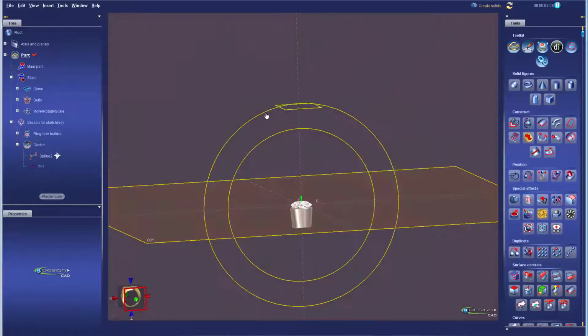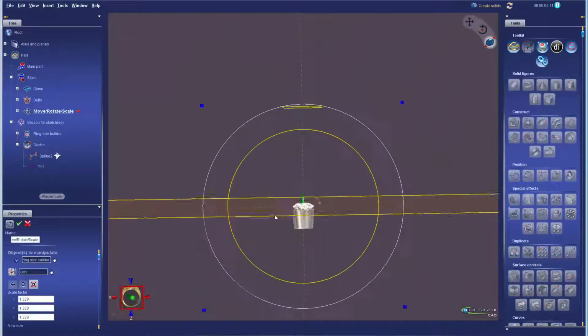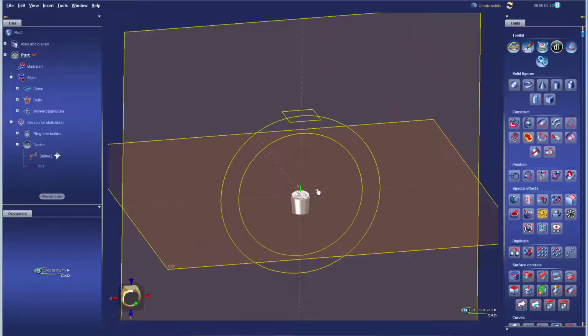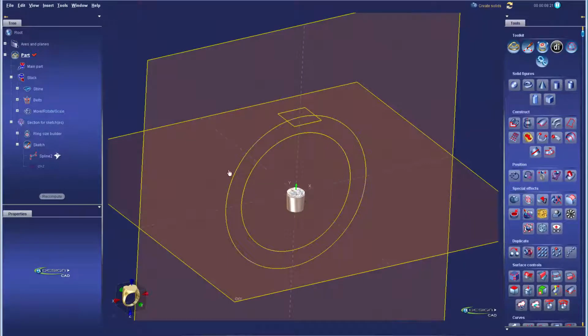The first thing we need to do is double click back on that curve and make sure that we set it to 2.5 millimeters using our top plane as a guide. Validate that. The next thing we need to do is also make sure that it matches a support of some sort. If we try to run stones on it now, the stones are going to flip around. They're not going to match a ring. Some will be flat, some will be flipped over. So to do that, we'll create a temporary solid to link it to.